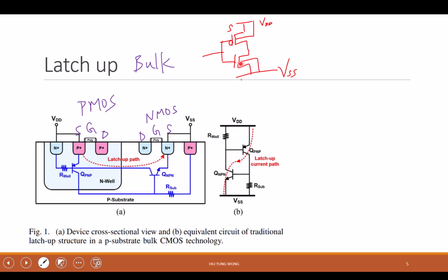And then you have this substrate connected to the VSS. At the same time, the source connected to VSS. Here is not shown, right? We should connect these two together. Then it becomes the output of an inverter, right? So in your assignment 1, you are doing a layout of ring oscillator, and what you are actually doing is 3 copies of this part in the real silicon, right? But now we are only talking about the inverter. So this is drain, this is the gate. Okay. Now, this is the problem.